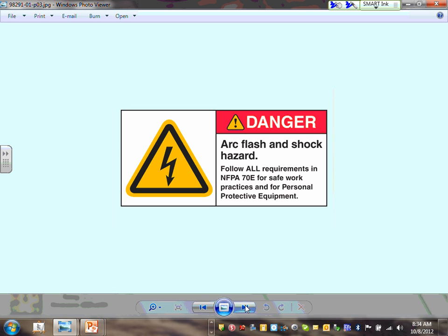You're going to have a big ball of fire burning you. You're going to have extreme light that makes you blind. Extreme noise, it's going to make you deaf. And if that's not enough, you're going to have a wave of pressure that pushes you off the ladder and tips you off so it can break your neck. So you can't have a worse scenario than that. So take it serious. Take it very, very serious, guys. I used not to take it serious until I read and saw a lot of incidents. You can lose your life. I know we're not electricians, but you are going to be around the electrician.